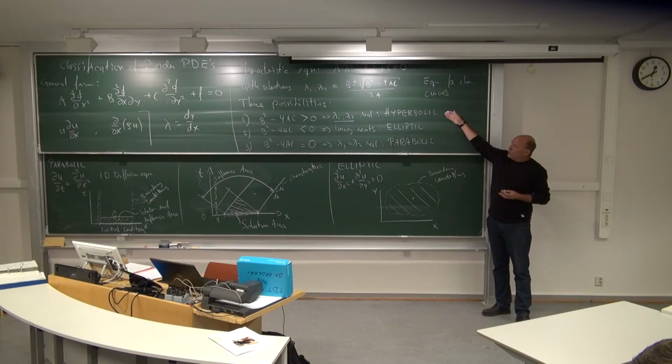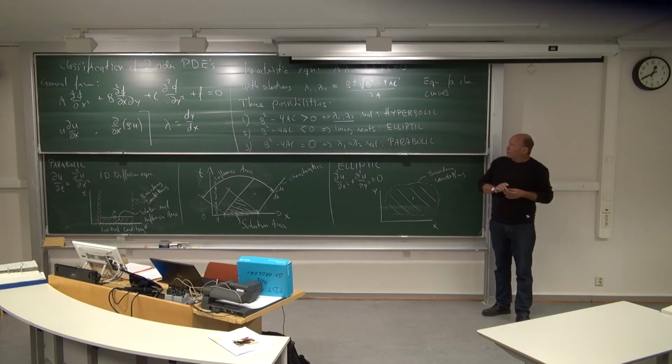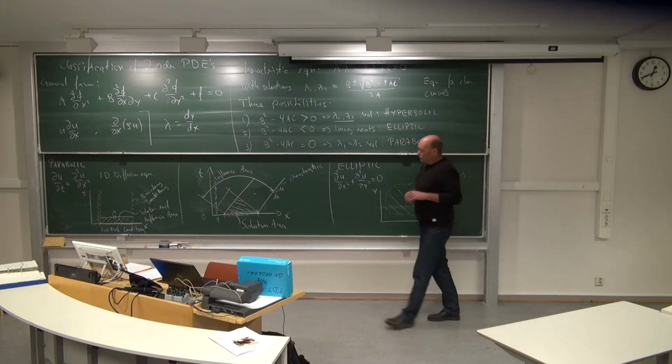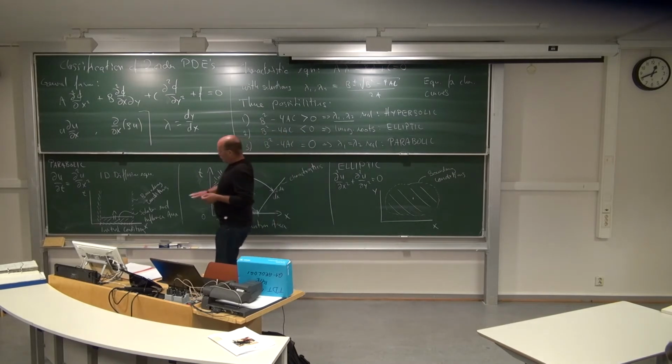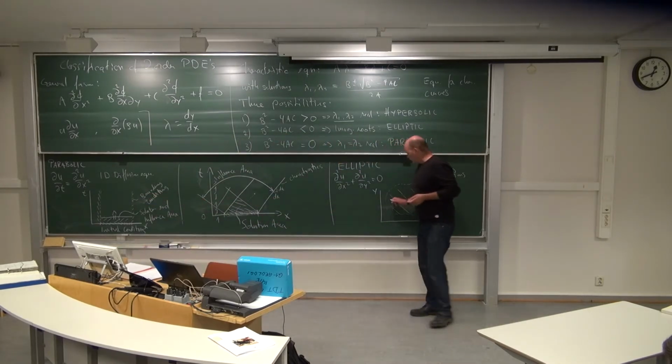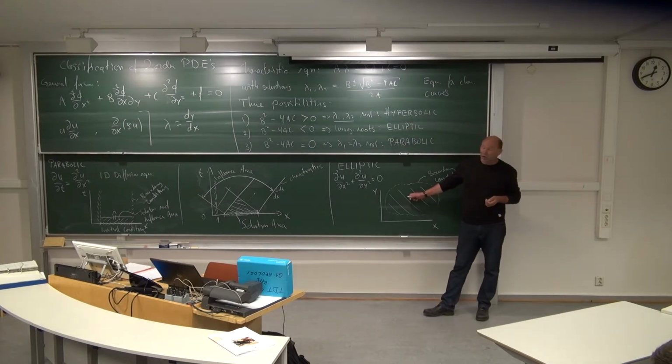The hyperbolic nature we can avoid if we say the density is constant, incompressible flow. Then the speed of sound is infinite, so you can't have any shock or anything like that. Then we are left with parabolic in time, but it still is elliptic in space.